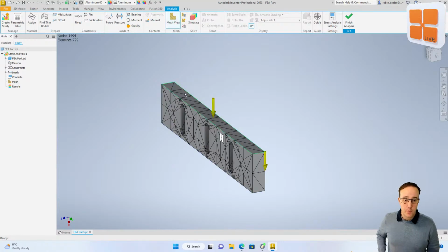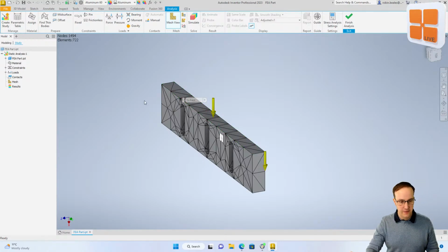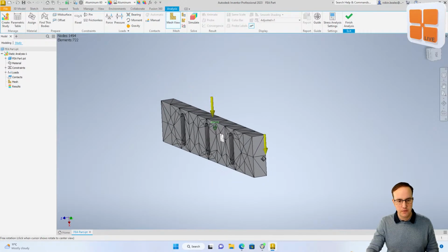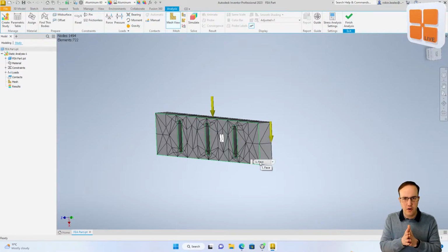To create a simulation, we have to create a mesh. The mesh will basically triangulate this component and turn it into a mesh. So we get all of these triangles, and the simulation is carried out on the triangles rather than the entire solid lump. It works with each of the triangles individually and sees how they react with one another, and therefore gives you a much more accurate and a much quicker representation than if you are trying to do the whole thing on a solid lump.